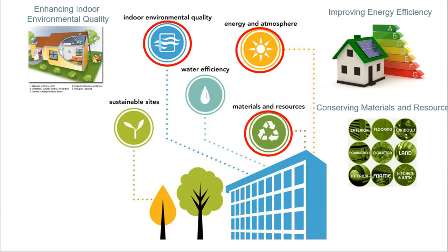So the acoustic is not going to bother the occupants when they're living in or using your building. So we say thermal comfort, lighting, and acoustic, and indoor air quality, which is becoming more and more important lately because of the recent COVID pandemic. We have to maintain a high indoor air quality for the occupants. Just providing mechanical ventilation may not be enough. You may need to enhance the indoor air quality along with mechanical and also active ventilation, which is basically opening your windows.